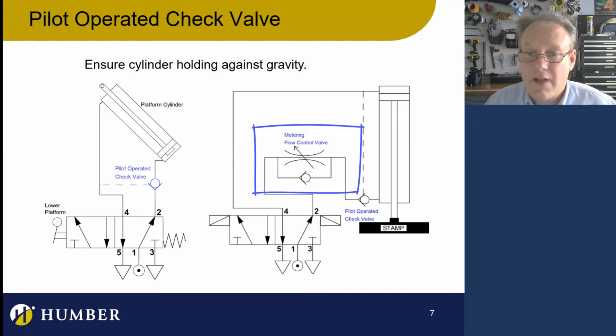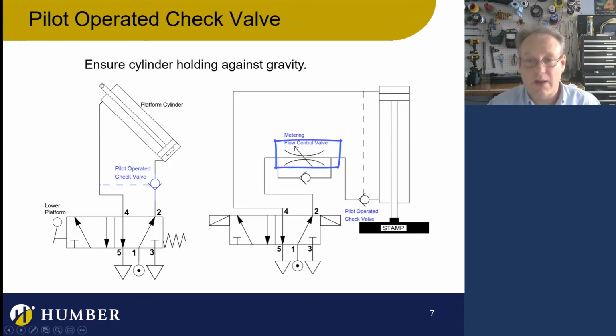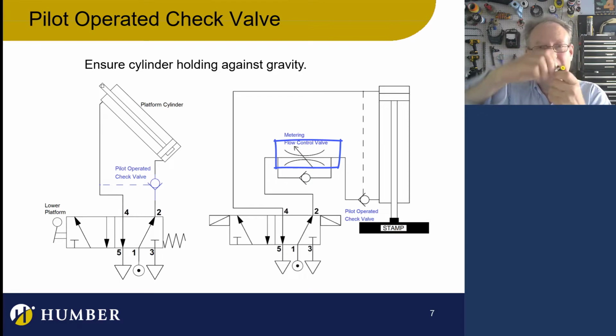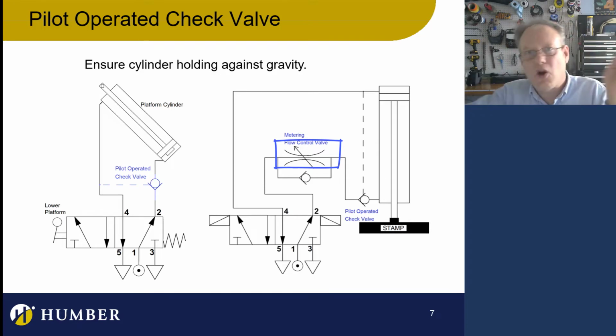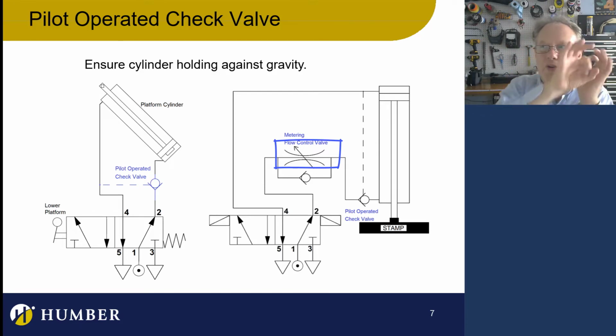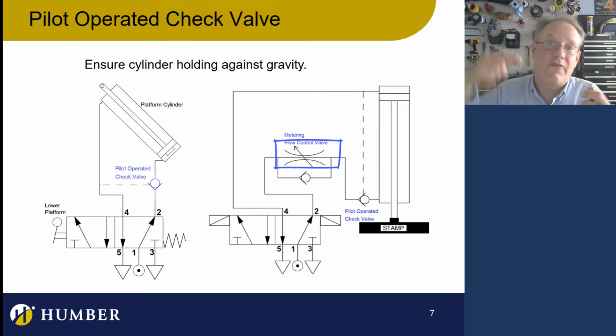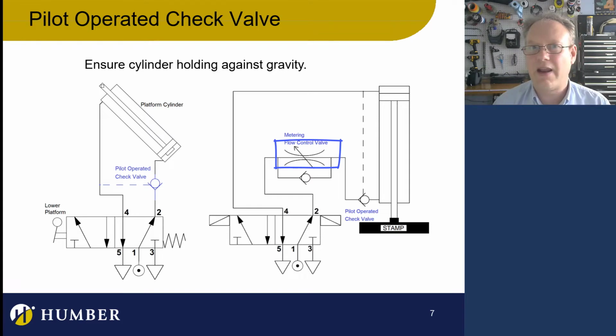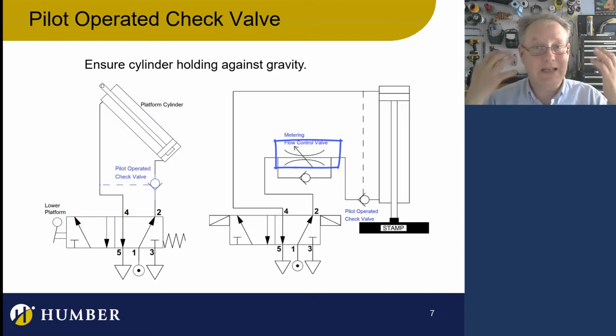We can see here that I've got a throttle valve, which we'll talk about a little bit later. But a throttle valve, I'll just tell you now, is something that actually throttles the air. So that screw on here is actually going to throttle the air. It just puts a little pin into the orifice of the air going through that area, and that air has to go past the screw, and the further the screw is into the orifice, the less air it's going to allow through, and it can block it, especially if you turn it all the way, then it actually blocks it completely.